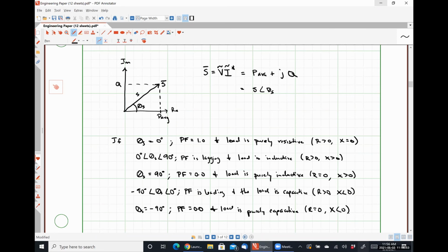The lights in this room definitely have some resistance associated with them because there are wires connecting to the end caps of the fluorescent tubes and all that kind of stuff. But I think the negative resistance of the bulb itself, or the mechanism by which light is emitted from the bulb, is significantly larger than the series positive resistance of the wiring.